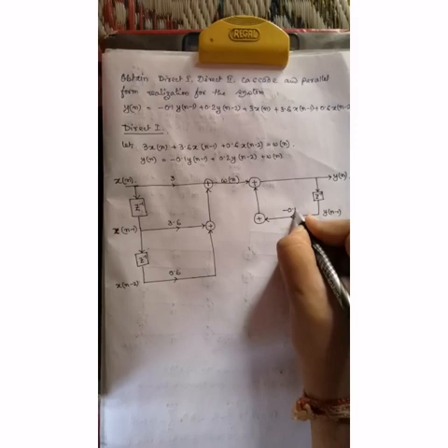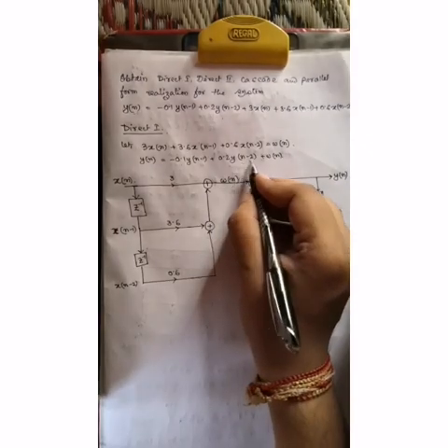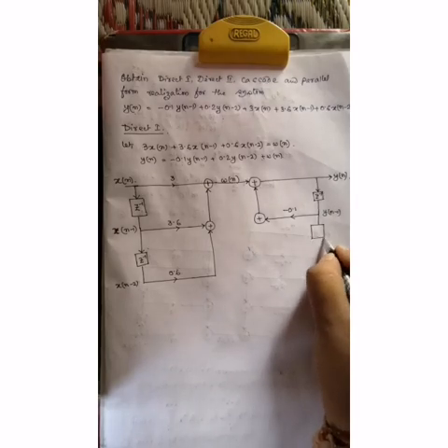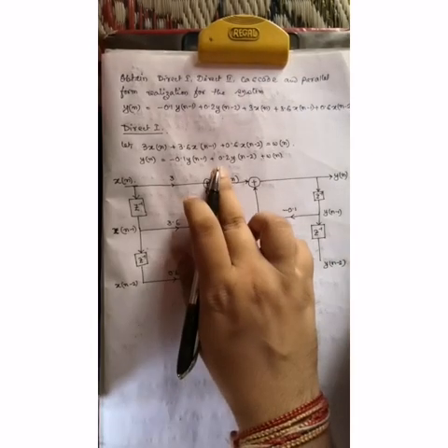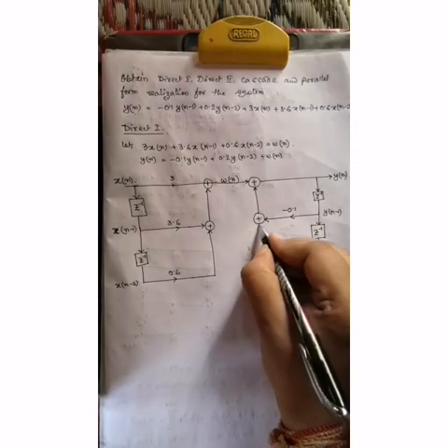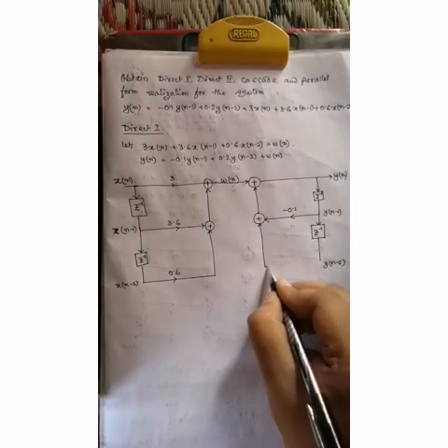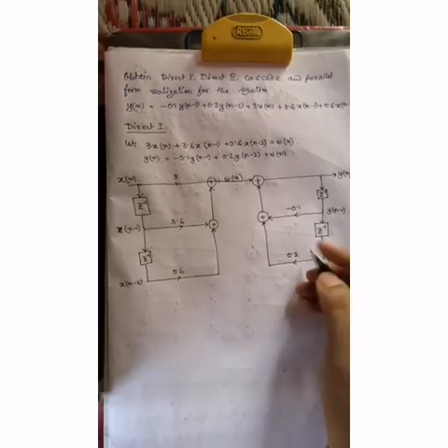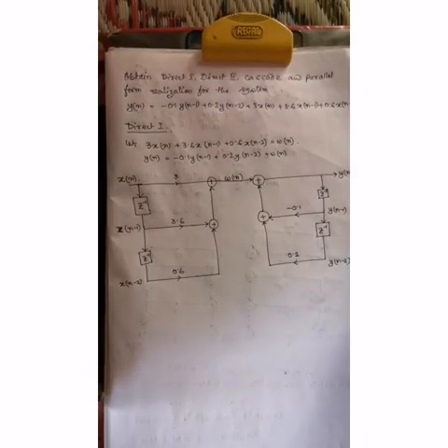The next part is for yn minus 2, so again we need another z inverse. Now the value becomes yn minus 2, and the coefficient is plus 0.2. So that's all for the direct one.